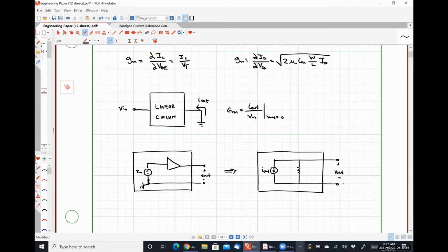Like so. So let's talk momentarily about first, why we have I out with this particular direction. So if we short circuited this and measured the current flowing in, which is how we would go about determining the transconductance, we would see that we would measure this exact current I out, and it would have a direction down because it was flowing into the output terminals.